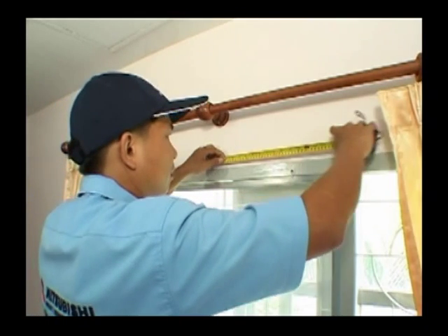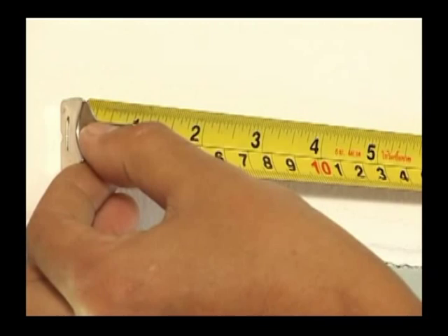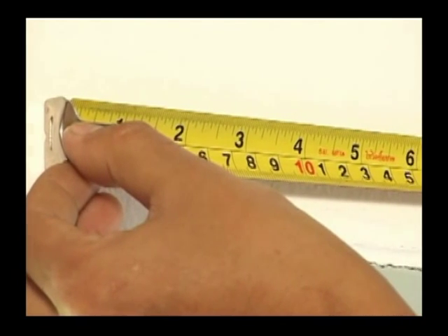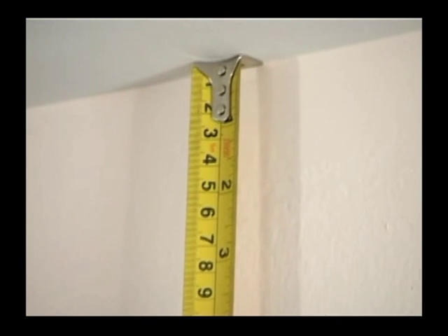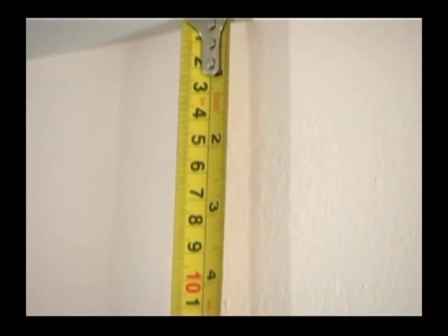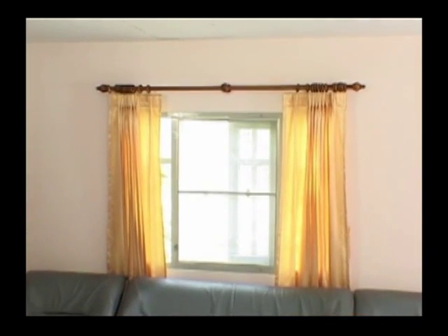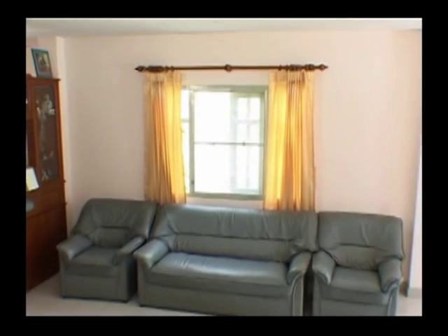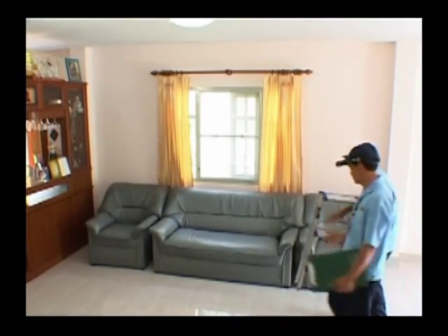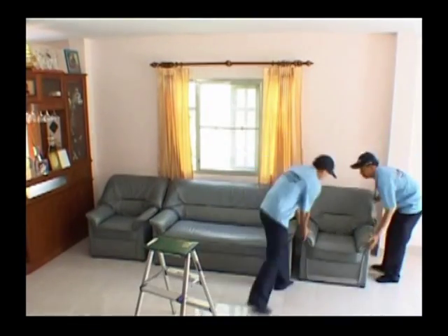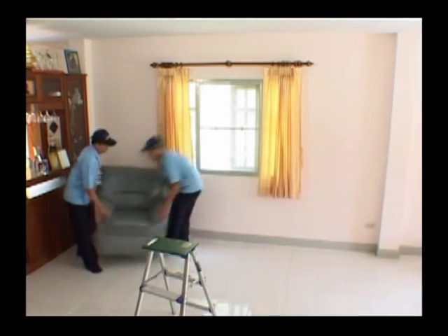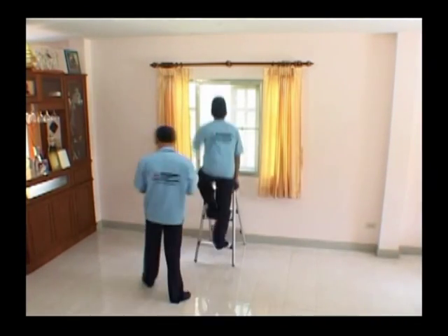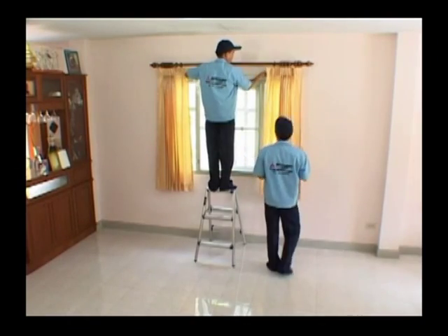The left side of an air conditioner requires a clearance of about 5 centimeters, and the right side and the top about 10 centimeters. The place must also be convenient for wiring and piping. The location must be easy for drainage and be at least 1 meter from a television or radio to prevent the interruption of audio and visual signals.